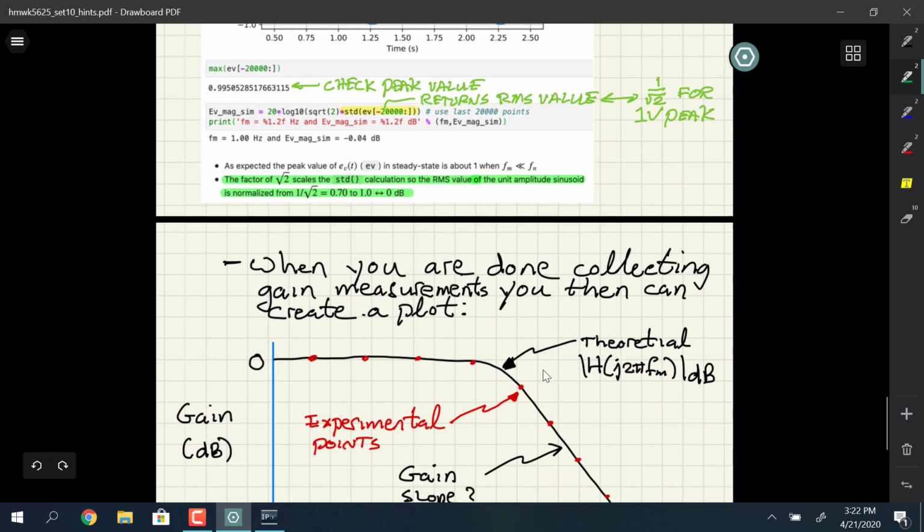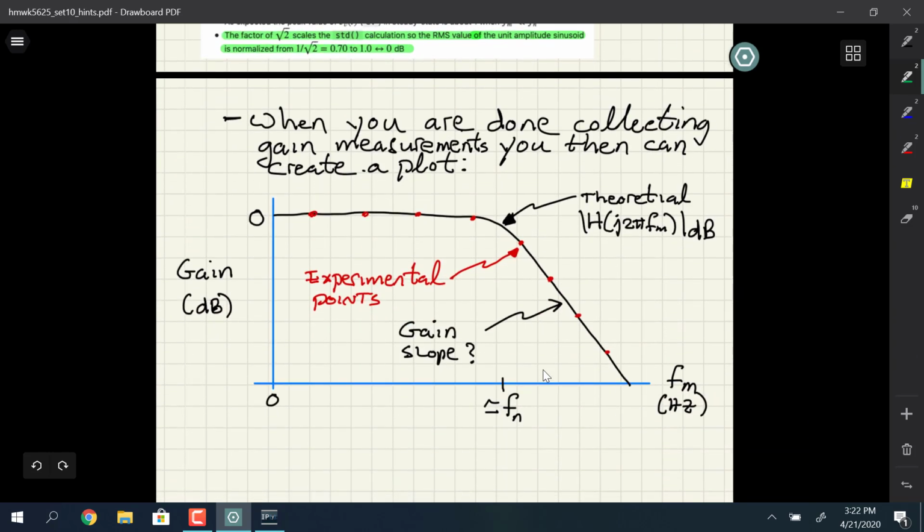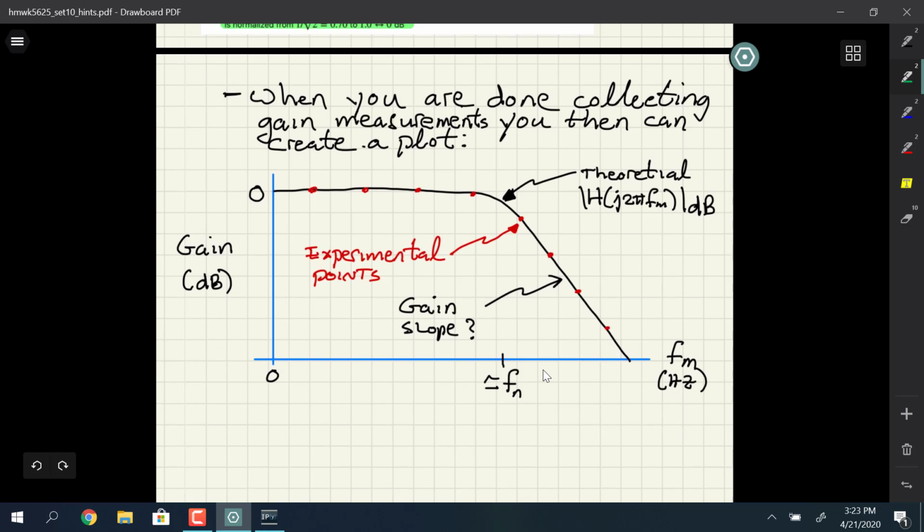We'll drill into this, but today I said I want this as your plot. So you're going to have a theoretical curve, which is the black curve, and for the first order loop, it's just a first order low pass filter. And then I want this to be log base 10 of f. So this is like a Bode plot then. And I think I was looking in my plot and my solutions, which are on my other computer right now.